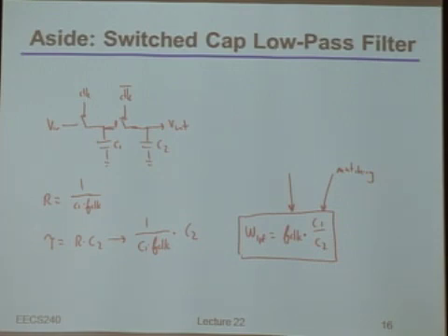But you're of course right, eventually you're limited by just how small you can make the C1 versus the C2, although even there's tricks you can play where, for example, you stack unit cells on top of each other, as opposed to putting them in parallel, that even then you can probably push this to be exceedingly low frequency. It's a very good question, though.